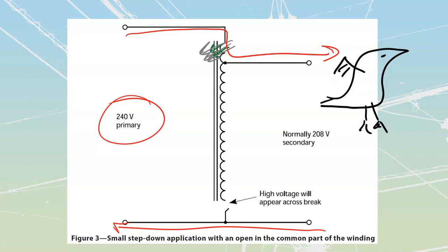Because what the hysteresis curve is showing is we've got a BH graph that centers across there. And as we increase the amount of magnetization across here, we're going to see an increase in the amount of flux until eventually the flux tops off. And then that's going to be it. And then we drop our magnetization in the opposite direction. Because it's AC, the magnetization changes direction. And so then we are going to drop the amount of flux, and then we're going to build rapidly in the opposite direction. It kind of goes back and forth like this.